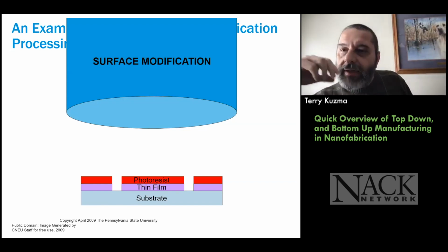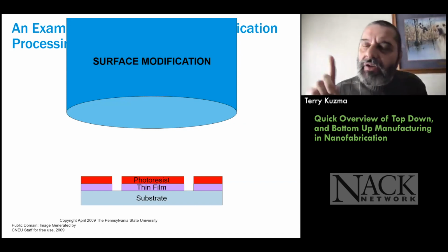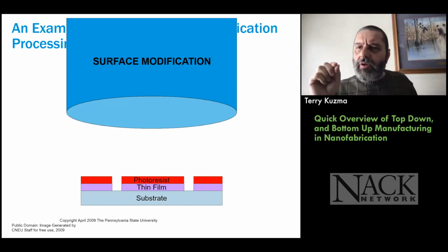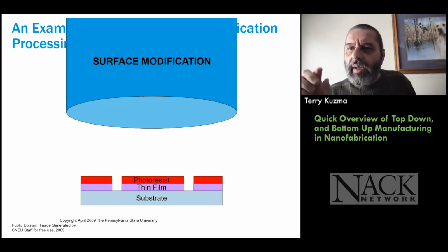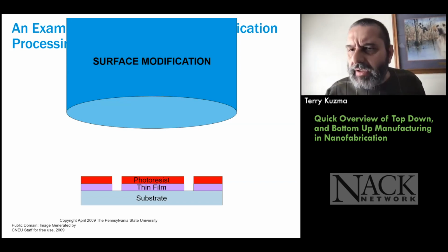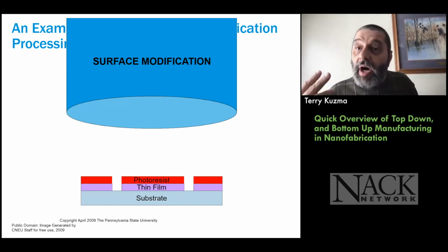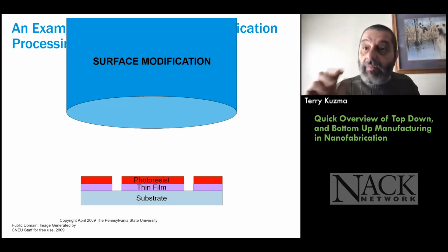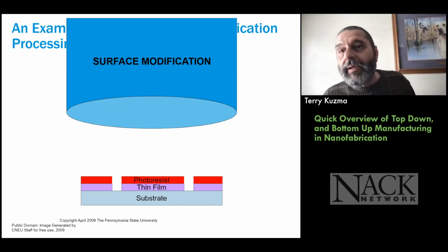So we can do things like we would get arsenic, and we would use arsine, the gas form. Why? Because we're doing nanotechnology, and when we want to do an atom at a time, a gas molecule is discrete. Does everybody see that? So gases are a good choice because they're atomically small. So we would take something like phosphine, which is phosphorus, but in a gas form. Also something they used like phosgene in World War I to kill people, right? So things like arsenic gas, phosphine gas, they're way wicked stuff. Does everybody see that? They use bromine too.